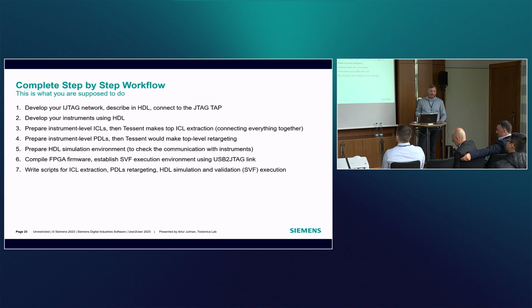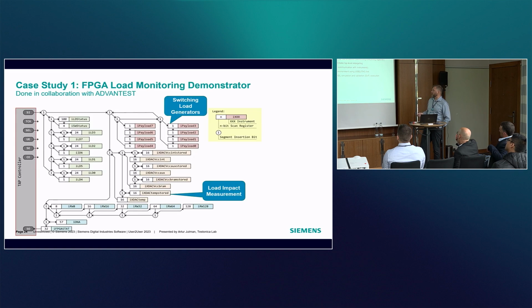Either you do it on a tester like the Advantest tester, or you can use some FPGA vendor tools to run SVF, or, as we do, use some in-house tools to run SVF over JTAG. Everything requires script development as well.